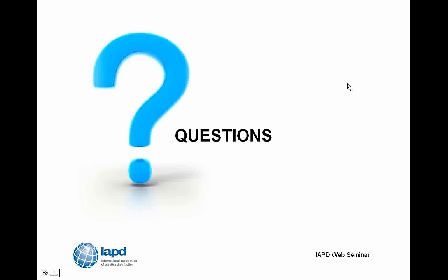All right, and the previous question asker, the PVC and PPL, he was referring to polypropylene. Oh, okay, I apologize. So if we look at PVC and polypropylene, could you re-ask the question, Wendy? Compare PVC and polypropylene for HDT. Won't polypropylene deflect at 264 psi and lower temperatures? Well, I think it would depend on the type of polypro and the type of PVC. They both tend to be low temperature materials.